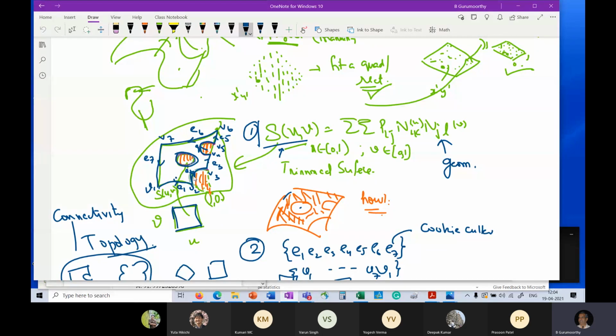So if I have a surface that has multiple boundaries, as in this case there are two, or if the boundary has more than four elements, then the representation that we had studied, like the NURBS or the Bezier or the parametric cubic, will not suffice, because these always map to a unit square, and therefore they will always be four-sided surface patches. But in real life, engineering artifacts, you will find that you will need various cutouts in your surface, and therefore the question was, how do we represent that?